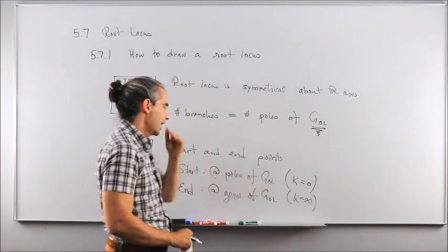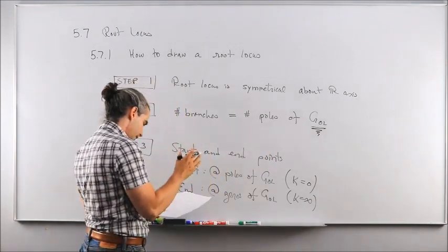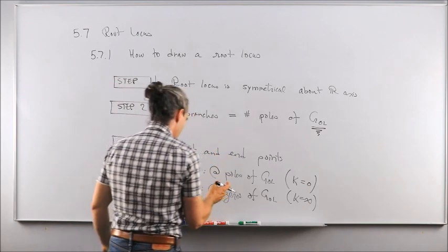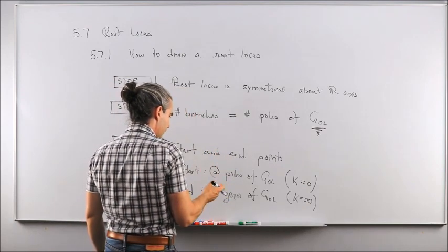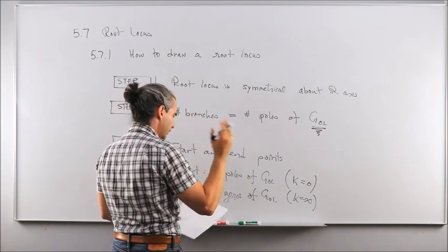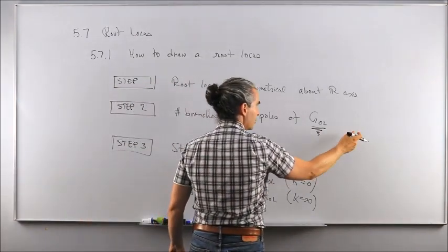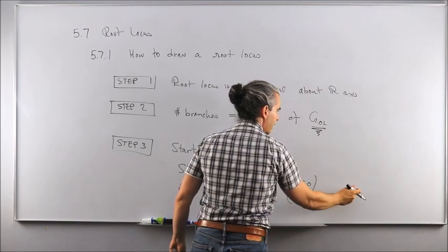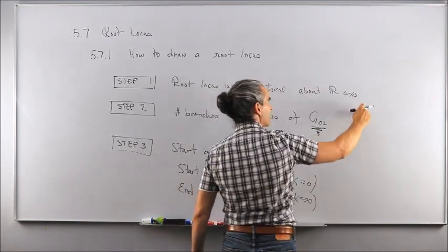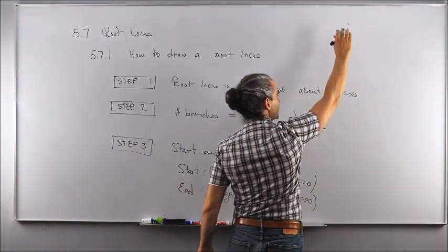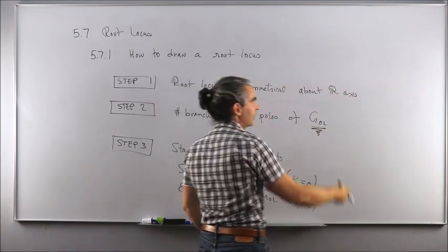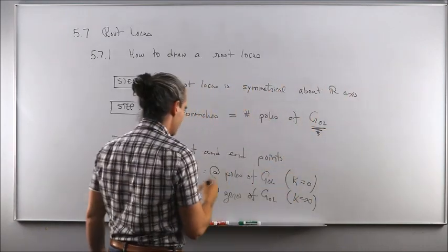Well, in that case, the poles would simply fly off to infinity along asymptotes. We had 2 asymptotes, one straight up, one straight down, and you saw that the poles would end up flying to plus infinity and minus infinity along those 2 asymptotes. That's what we mean here.